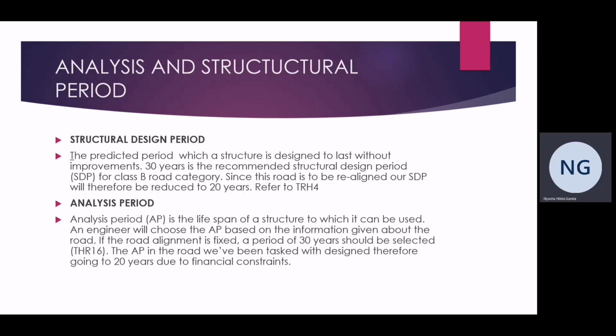Analysis and structural period. The structural design period is the predicted period for which a structure is designed to last without improvements. 30 years is the recommended structural design period, SDP, for a Class B road category. Since the road is to be realigned, our SDP will therefore be reduced to 20 years. We can refer to this, as we use the TRH4.